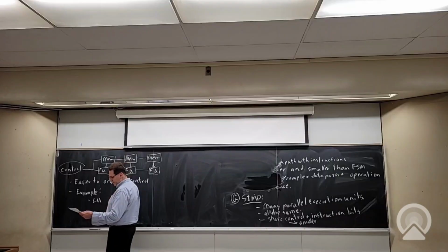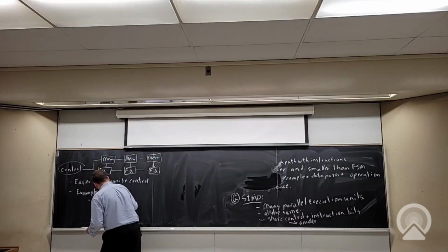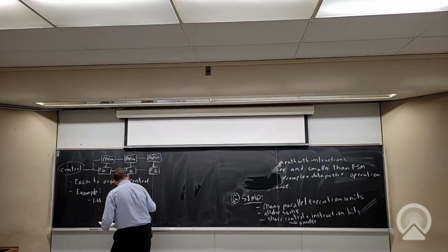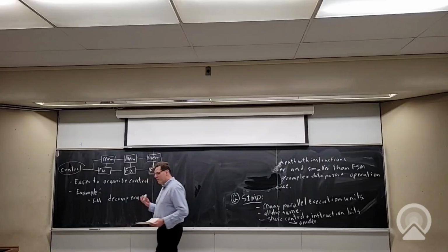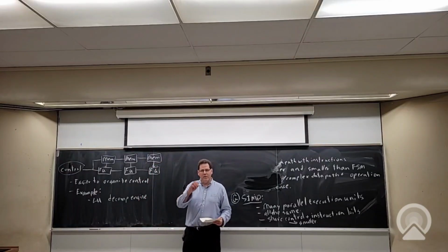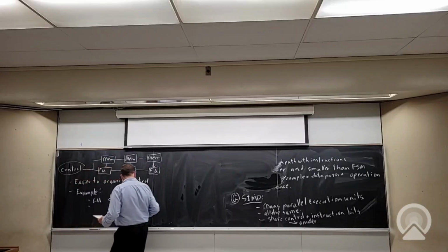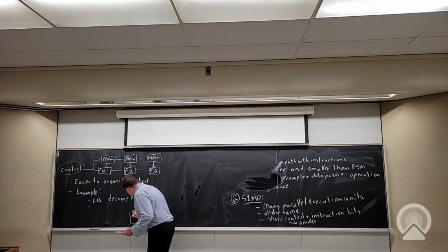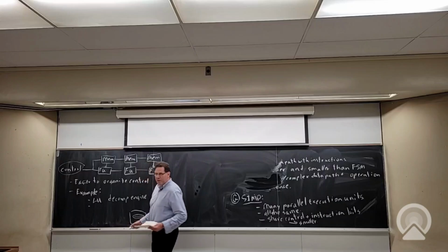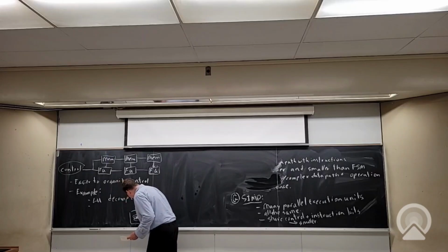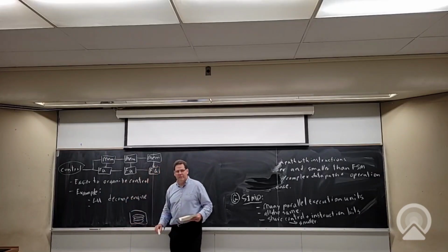So we accelerated it with an FPGA. Okay, so we made an LU decomposition engine. It's basically doing something like Gaussian elimination, right? Take all the data in this row, scale it, subtract it from the data below, and repeat this many, many times. So because it's taking all the data in this row, for example, of a matrix or a piece of this row, scaling it by some number means multiplying it by something, and then subtracting it from other rows is basically a whole bunch of parallel subtractions.